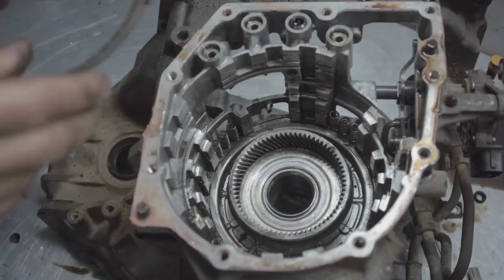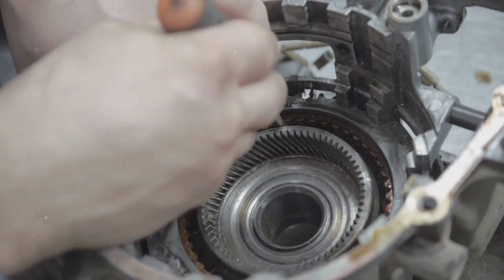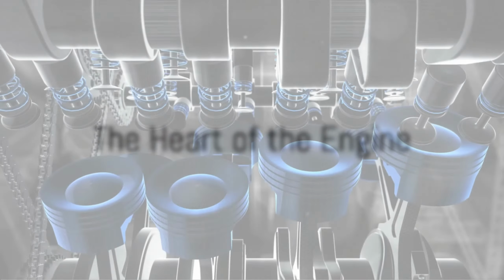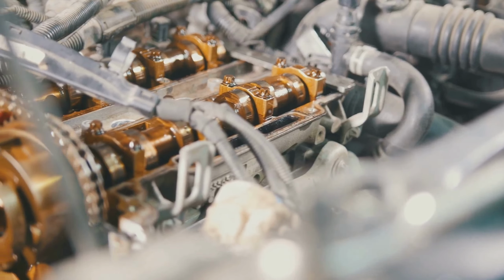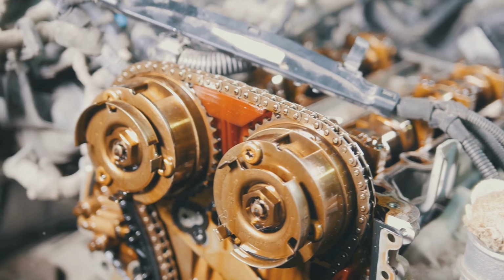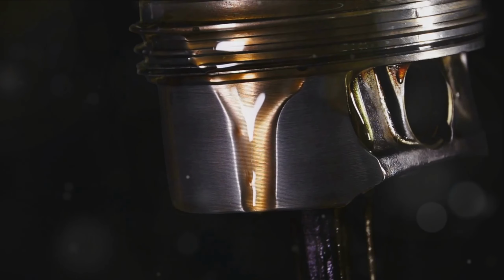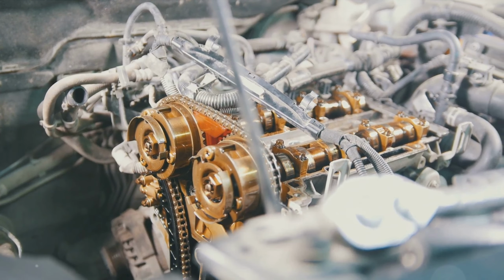The moving mesh and multiple reference frame models of ANSYS Fluent are critical tools in the automotive industry. The moving mesh model is used to simulate dynamic mesh motion and deformation. It's particularly useful in automotive applications where there's a need to simulate the movement of components such as the opening and closing of valves in an internal combustion engine or the movement of pistons.